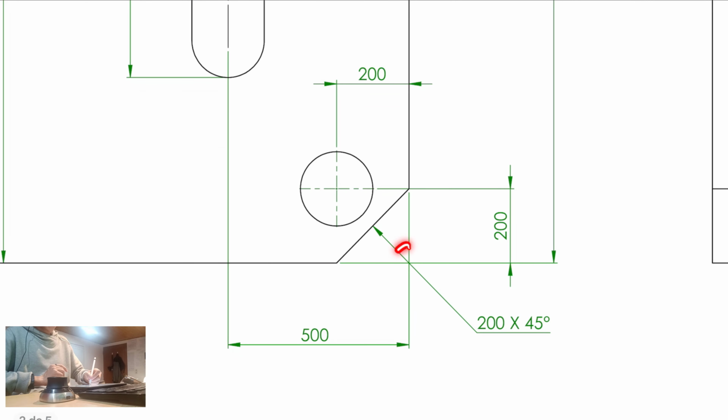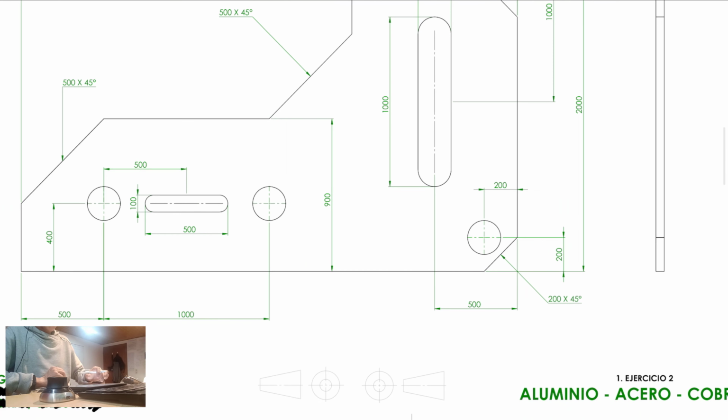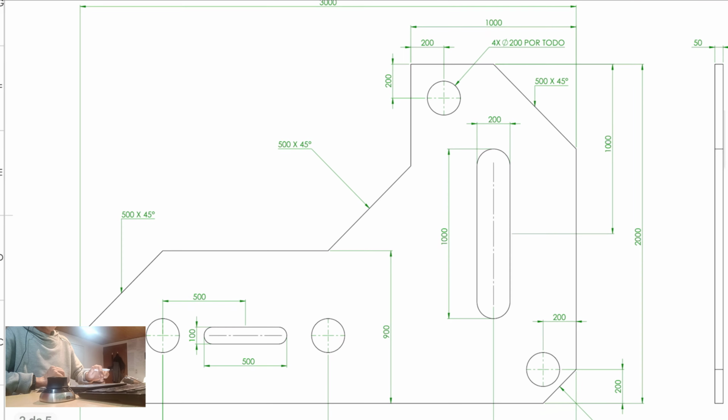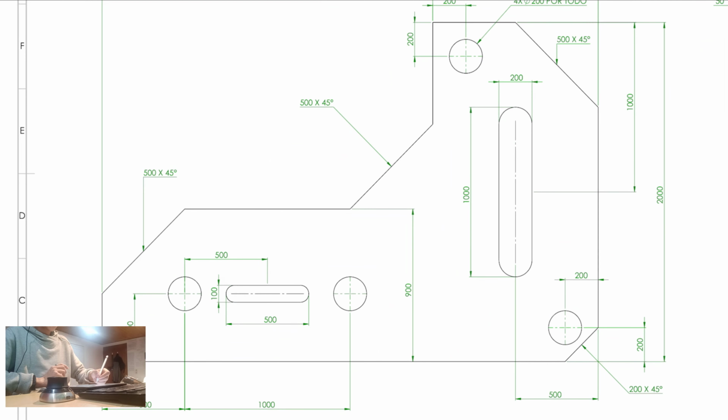Now, please be aware of this as well. Do not create cross dimensions. This is not well seen as well. And that is pretty much it. Okay, that goes to this dimension. Please try to not place the dimensions inside of the 3D model, okay, of the view. Please try to place them outside, okay? All right, so that would be pretty much it.